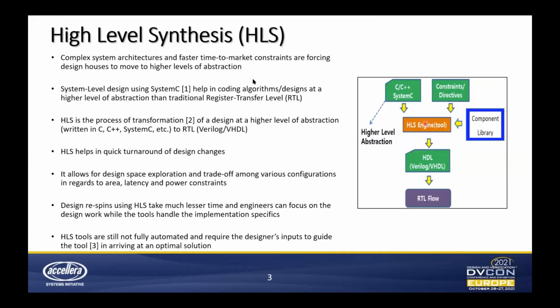The output of this HLS engine is nothing but synthesized Verilog and VHDL code that best satisfies whatever constraints and directives have been given to the HLS tool. So that's HLS in a nutshell. We are not going to get into how the transformation actually happens, which is nothing but a series of algorithms, but this is just the overview of what HLS is.